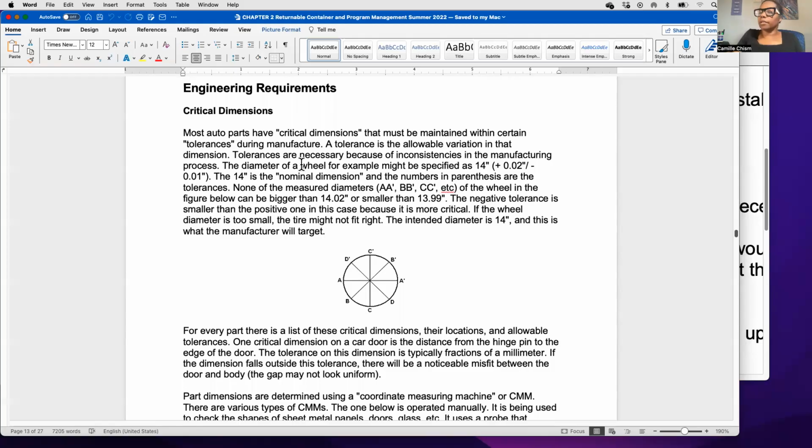The tolerances are important because if you have a part that is plus or minus 1/4 of an inch, which means that there's a 1/2 inch swing for the part, one way or the other. So one part could be 1/2 inch bigger. If it's on the high side of the tolerance, it would be 1/2 inch bigger than a part that falls at the low end of that range, if that makes any sense.